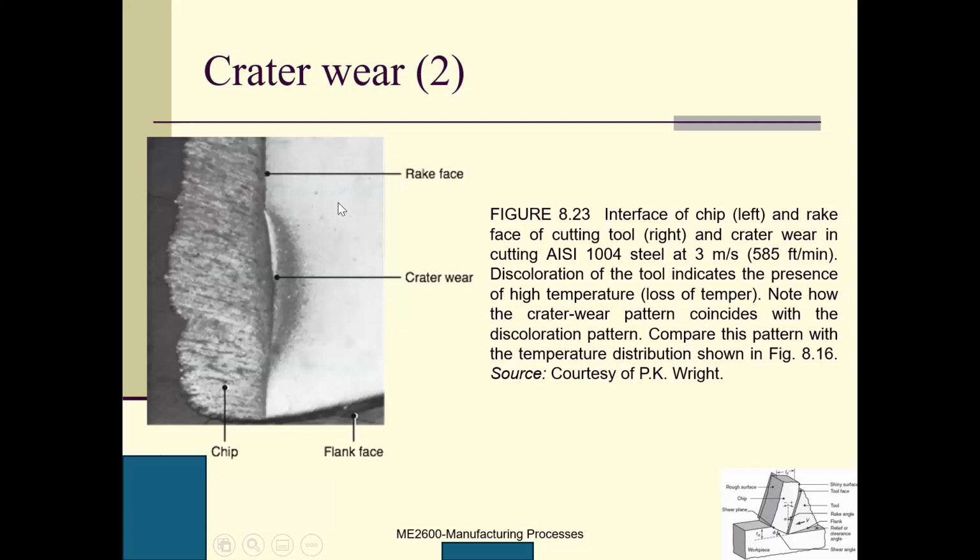So this is a chip. So this is our tool. And here you can see very clearly this is the crater, just like the craters we see on the moon surface, right? This is the crater wear, this is the flank face, this is the chip.